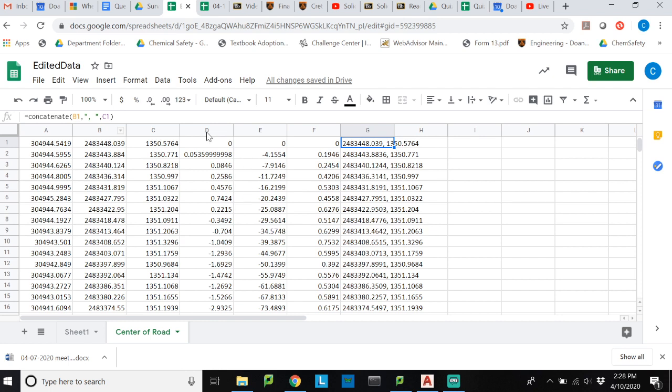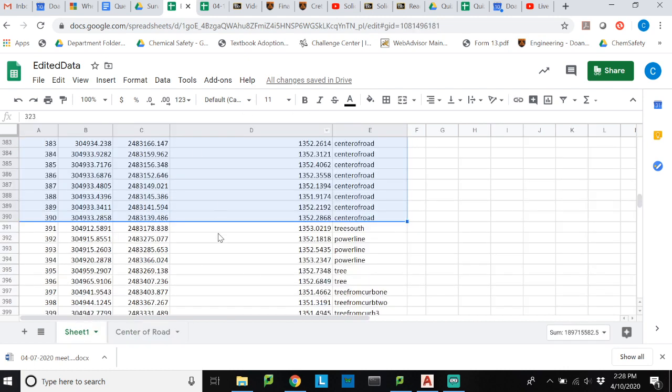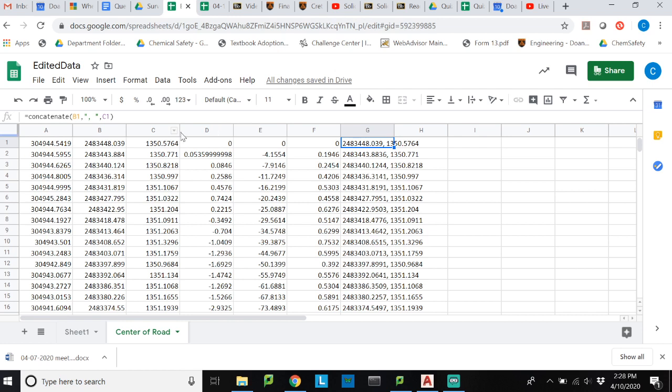Zeroing out these values means that your very first point for your center of your roadway starts at 0, 0, 0. If we import any other points, we have to make sure that we're subtracting these 3 exact values, or that you're copying and pasting to something similar. But that's up to you.